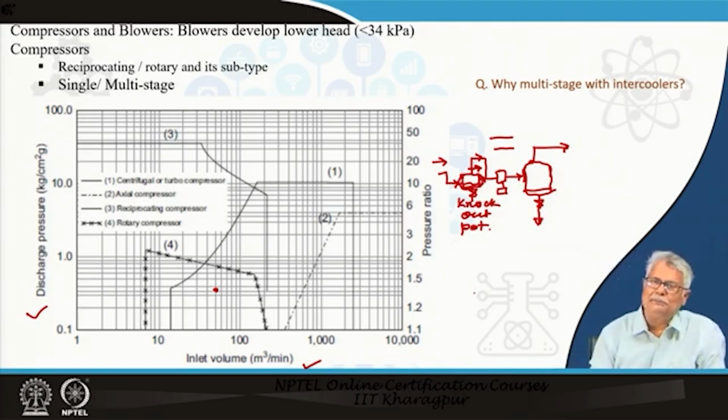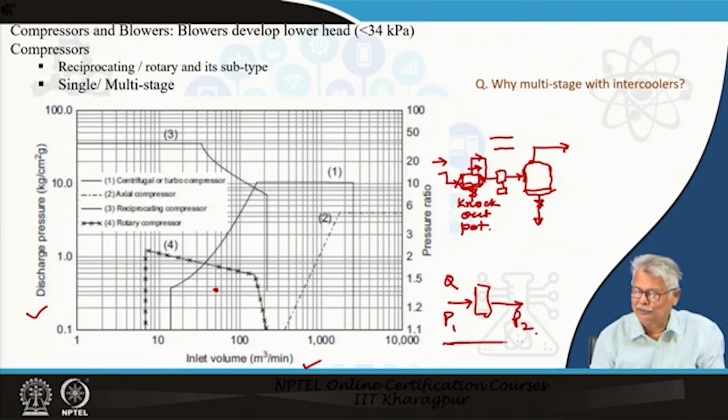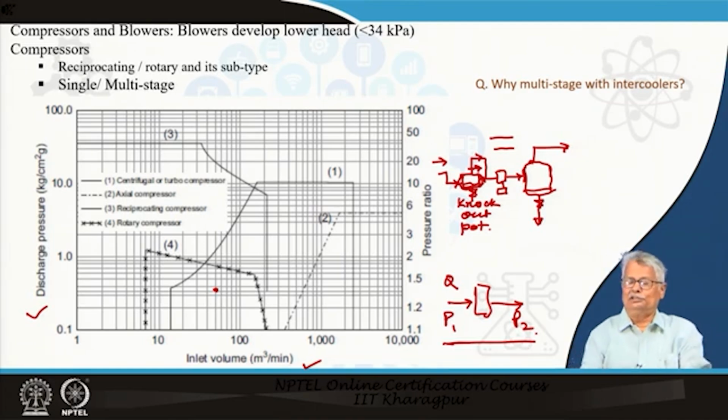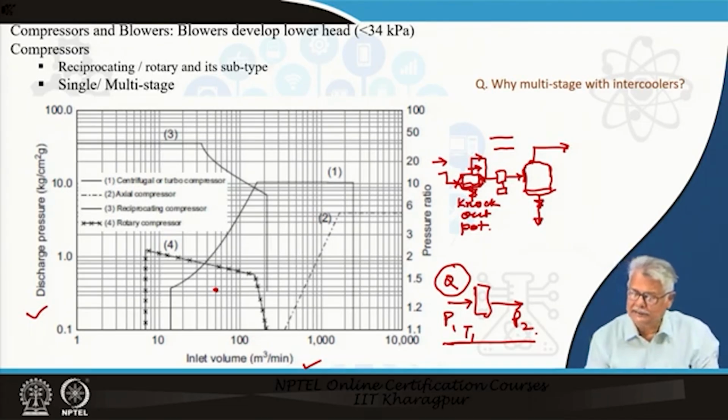I know the purpose of a compressor is to have a fluid at a pressure P1 and finally deliver it at a pressure P2. The mass flow would remain constant, and since the pressure changes from P1 to P2, the Q, if it is the volumetric rate, would come down at the discharge. And we have iterated many times that for compressors, this Q at the suction condition is definitely your capacity as per the convention in industry.